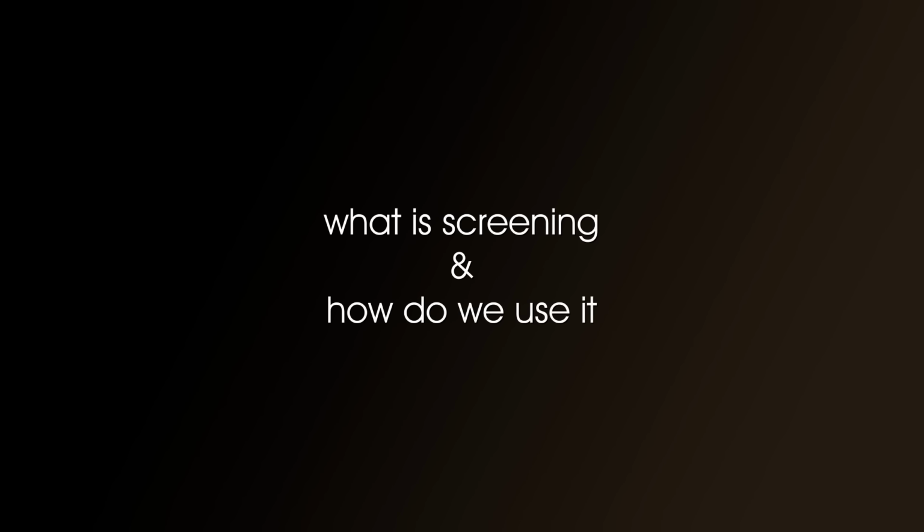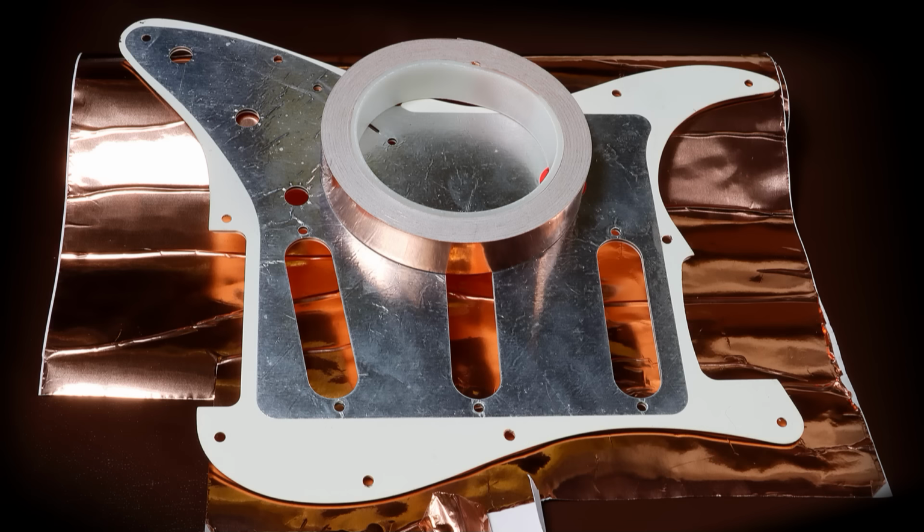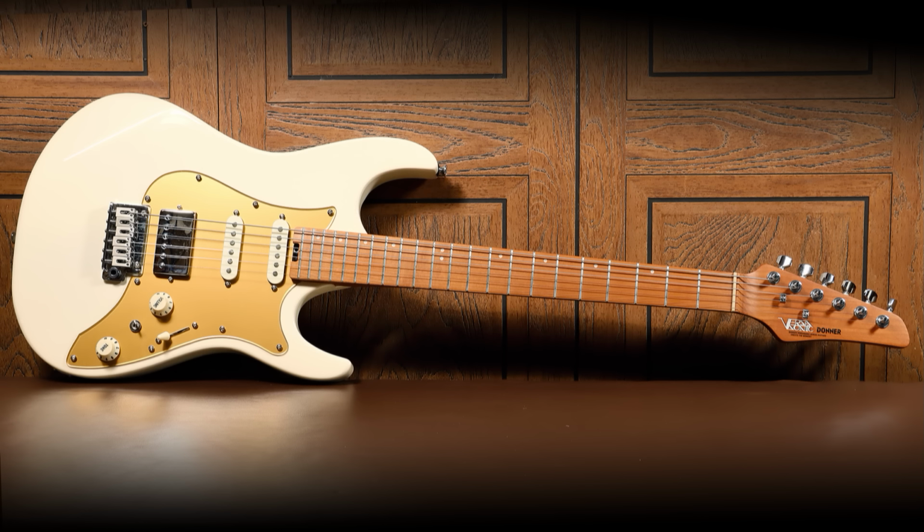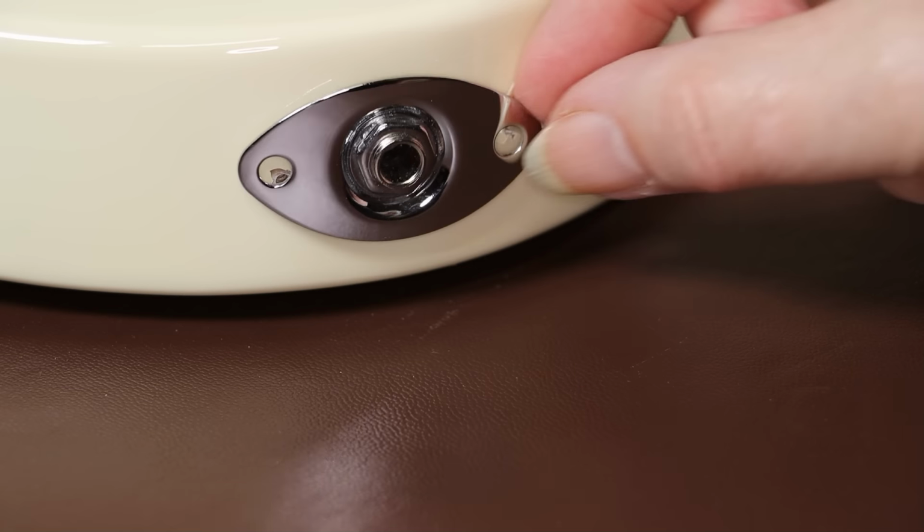What is screening and how do we use it? There's nothing really complicated or technical about screening. It's literally just an electrically conductive material that you can put between the outside noise pollution and the guitar signal. And when you're talking about a guitar, we can think of it this way.